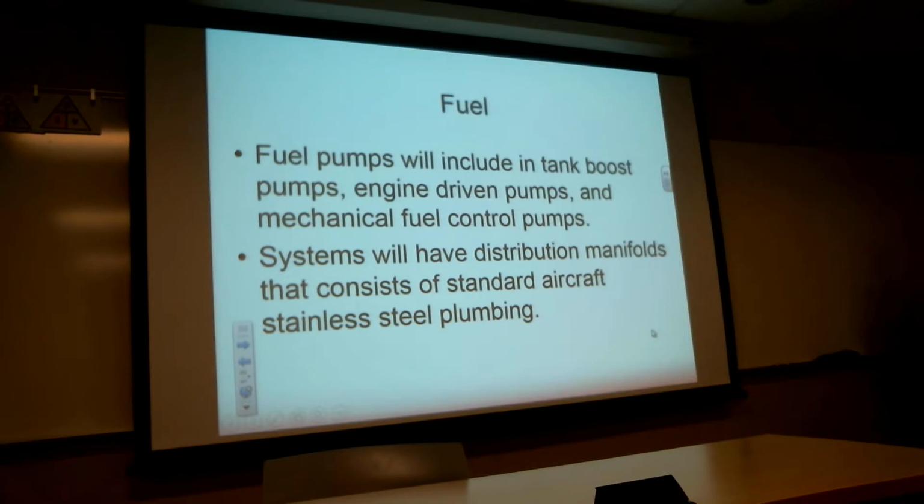So the systems typically are stainless steel tubing. There's very little flex hose on turbine engines. Maybe the fuel into the fuel control, but most everything else is rigid plumbing, stainless steel lines that are silver soldered together, or it may have joints with packings and O-rings. Not too much flexible plumbing on the fuel control on turbine engines.